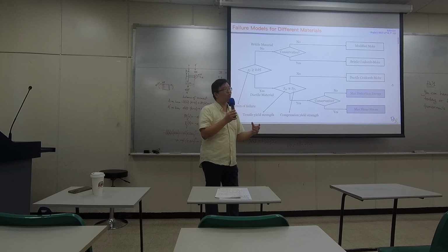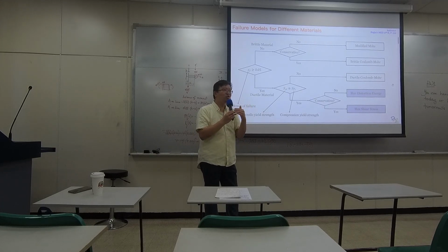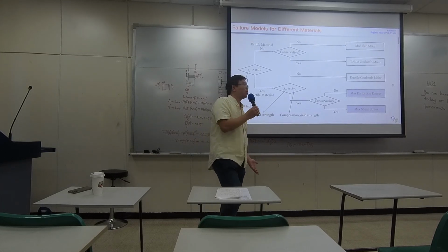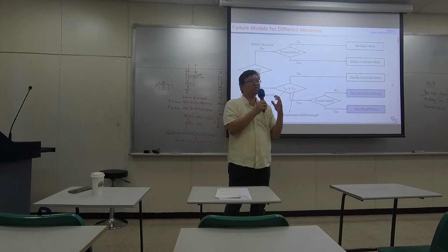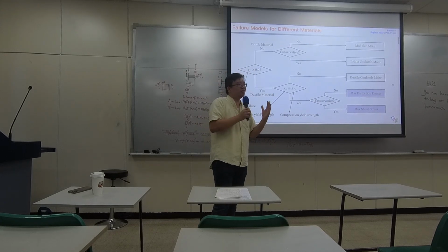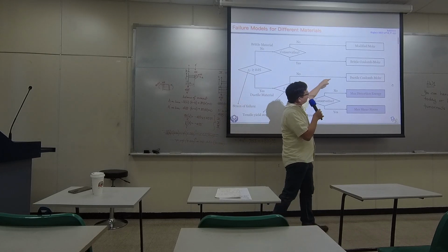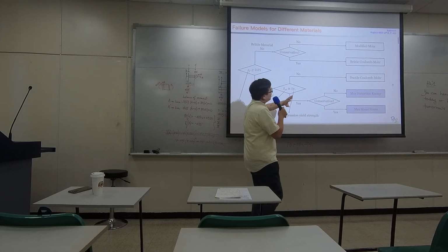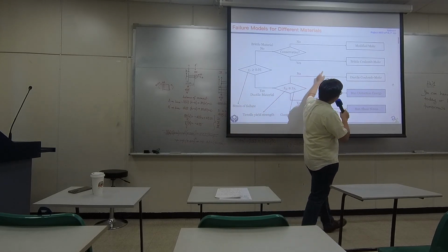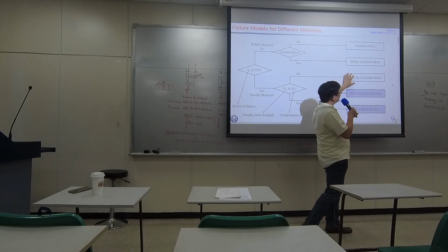You need to check whether your design equations for tensile and compression could be very different. If they are so close, probably it doesn't matter. But if a material can elongate better but doesn't compress as well, then you probably need two sets of equations, or just go to a different model. Just treat it like a ductile material. Oh, no, not like that. Let's just use a different material. And of course, still a ductile material, but a different model.